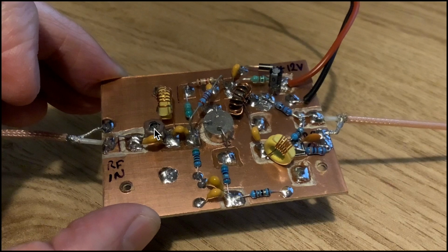And you'll see this is a trimmer because I wanted some variability in this, because when you're building this, especially building it Manhattan style like I do, there's all kinds of stray capacitance that you hadn't bargained on. So you can build it perfectly, but it still wouldn't be quite right because you can't model all this stray capacitance. So it's really useful to be able to adjust that. You can adjust the inductance, of course, by squeezing the turns together and pulling them apart a bit. Incidentally, don't do this. What I should have done is ripped this off and redone that, and rather than push all those together, I should have put more turns on there and spread them out, because this produces stray capacitance as fast as you can look at it. But anyway, do as I say and not as I do.